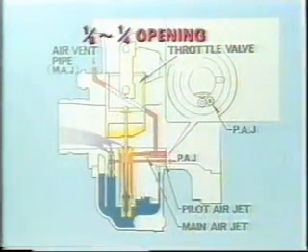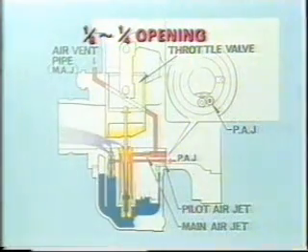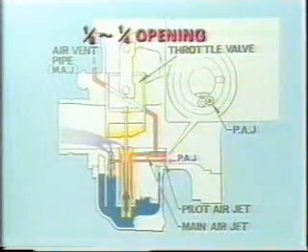When the throttle is open from 1/8 to 1/4, a fuel-air mixture is supplied from the pilot system. In addition, gas is also supplied from the main nozzle, since a vacuum is created. The fuel amounts from the pilot system and the main nozzle are primarily determined by the size of the cutaway of the throttle valve. When the size is larger, less fuel is allowed to flow. When the size is smaller, more fuel is allowed to flow.